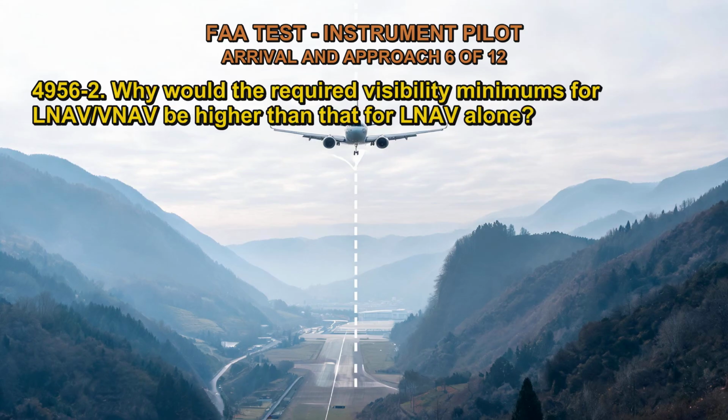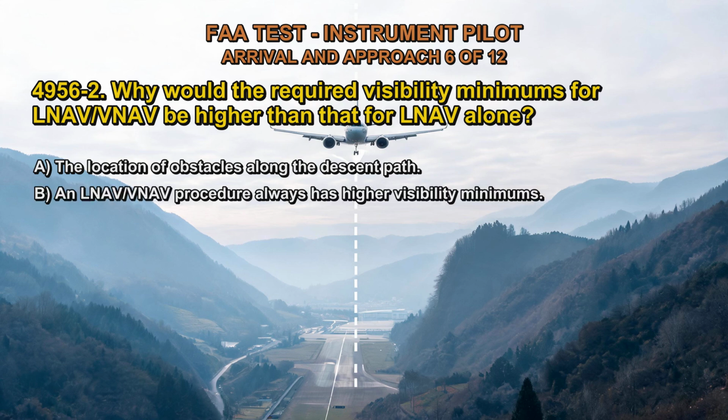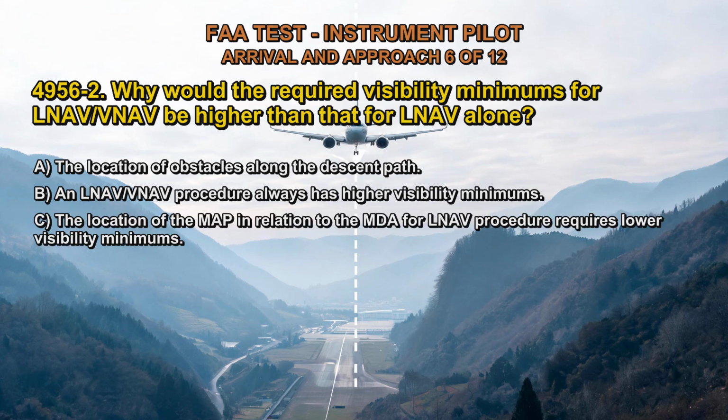4956-2. Why would the required visibility minimums for LNAV/VNAV be higher than that for LNAV alone? A. The location of obstacles along the descent path. B. An LNAV/VNAV procedure always has higher visibility minimums. C. The location of the MAP in relation to the MDA for LNAV procedure requires lower visibility minimums.